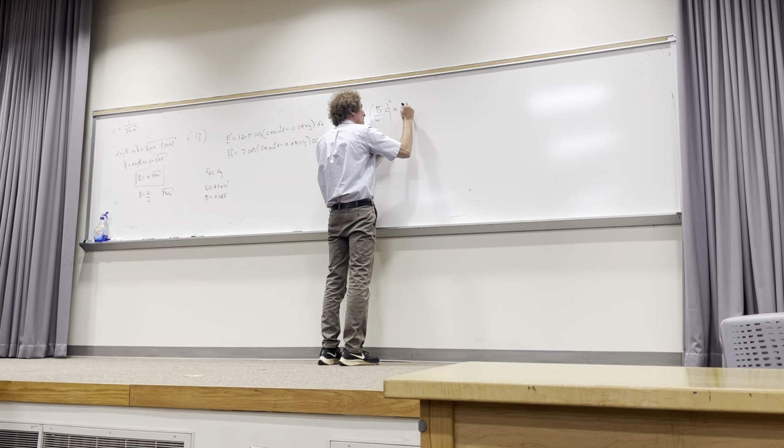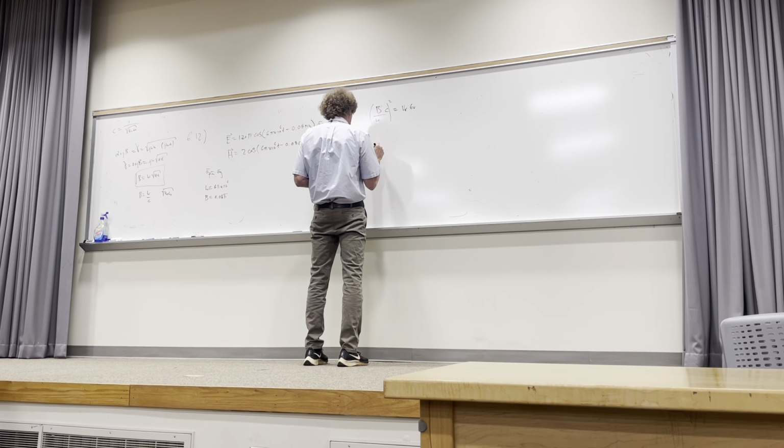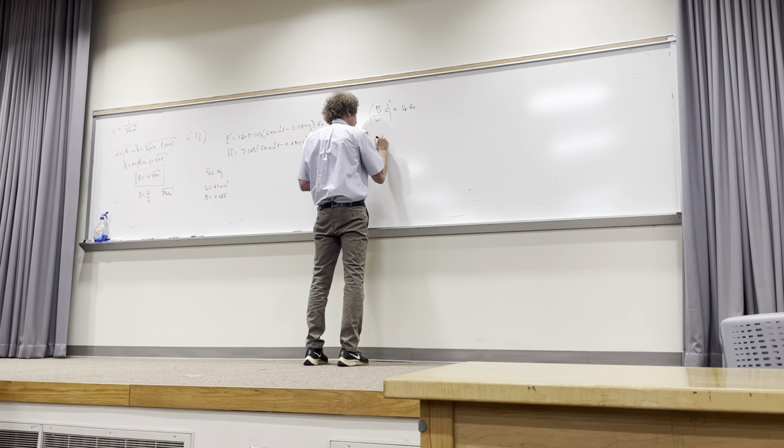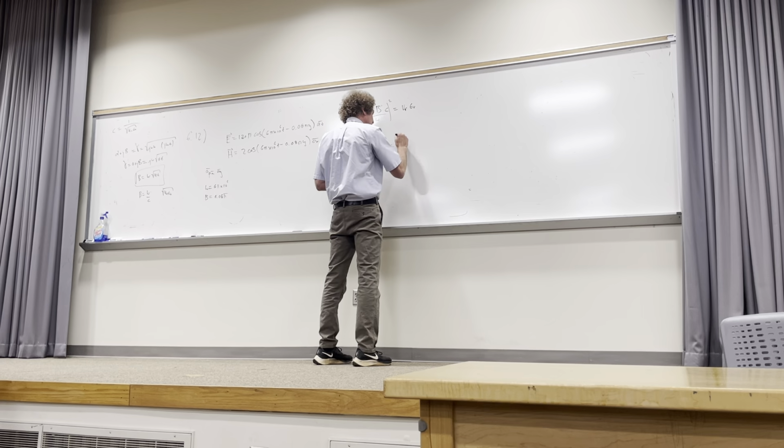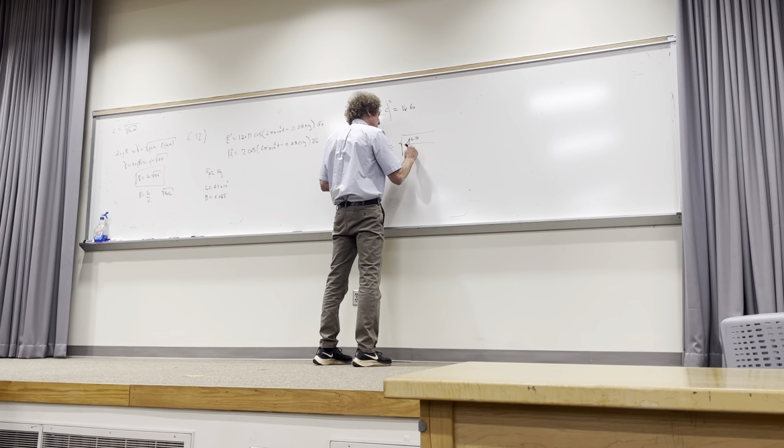All right, next thing we know is the ratio of the magnitude of E to H is the intrinsic impedance of the medium. That's equal to the ratio of, in this case, the magnitude of E over the magnitude of H. And the material parameters that involve eta, the general form is the square root of j omega mu over sigma plus j omega epsilon, right?